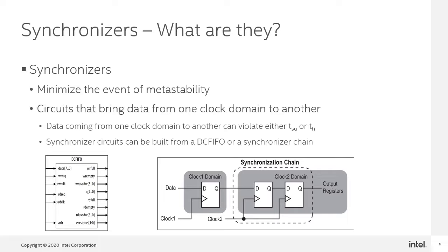The figure shows an example synchronization chain of length 2, assuming the output signal feeds more than one register destination. A metastable signal must resolve in the chain before the output signal is captured by multiple design registers.